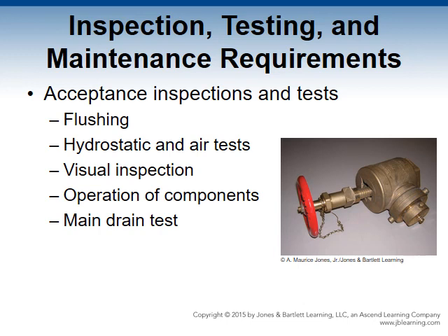The operation of components. Any component that is capable of movement, whether it be manual or automatic, requires an operational condition testing. Components that should be tested are as follows: your control valve, your movable fire department connection components, your water flow switches, your tamper switches, your drain valves, your automatic drip valves, gauges, pumps, automatic filling devices for your tanks, quick opening devices, dry pipe, deluge, alarm, and pre-actionary valves as well, and any device that regulates the pressure.